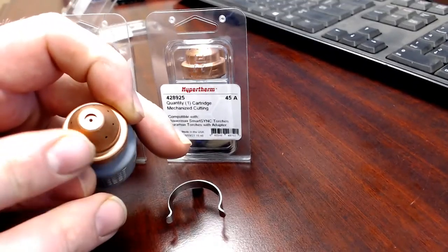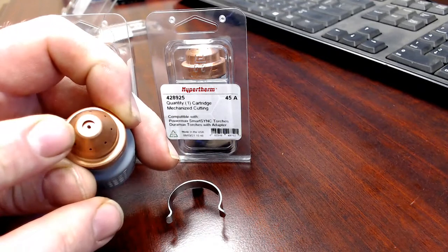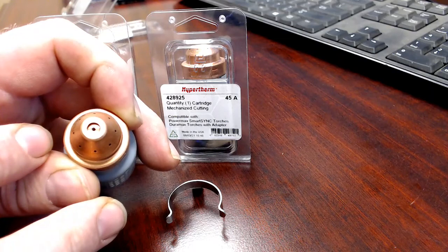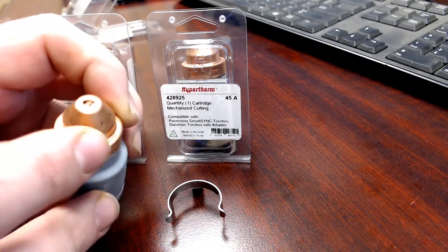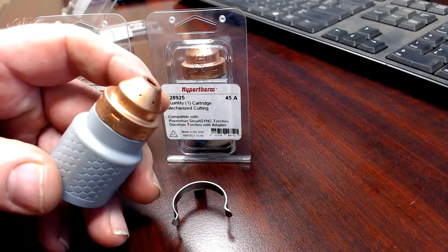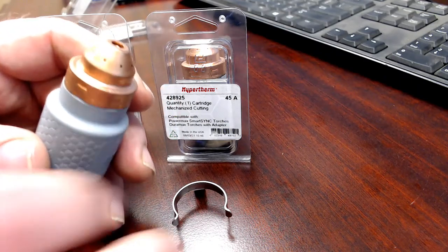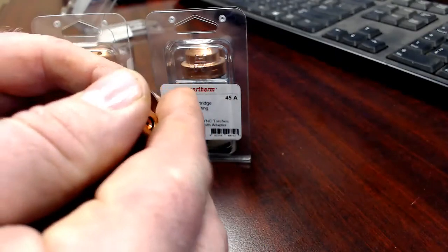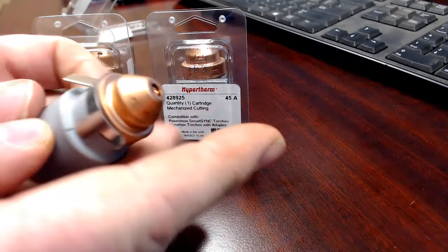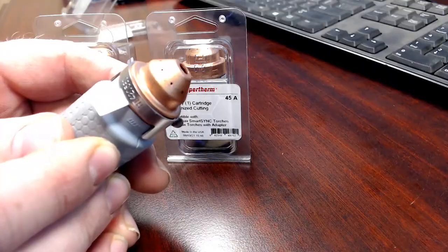The tip will work about the same as usual consumables. You'll inspect your shield, make sure that's clean of debris. Make sure that your tip is nice and rounded, not deformed, not egg-shaped. The rest will be taken care of by Hypertherm. The sync technology will actually shut this consumable off at its end of life. To run the ohmic sense, we'll simply just take our clip, mount that to our consumable. Now we'll just simply put our wire onto our cartridge, put it to use.